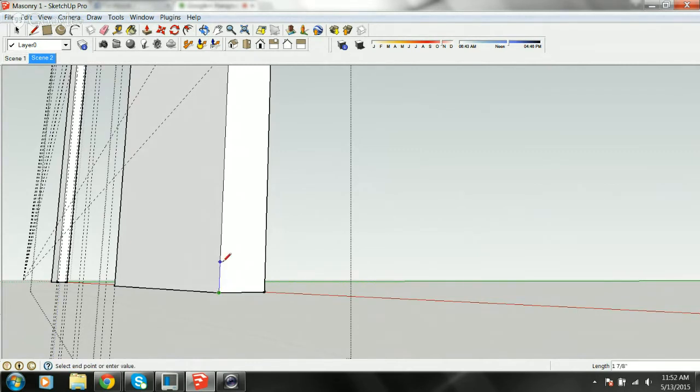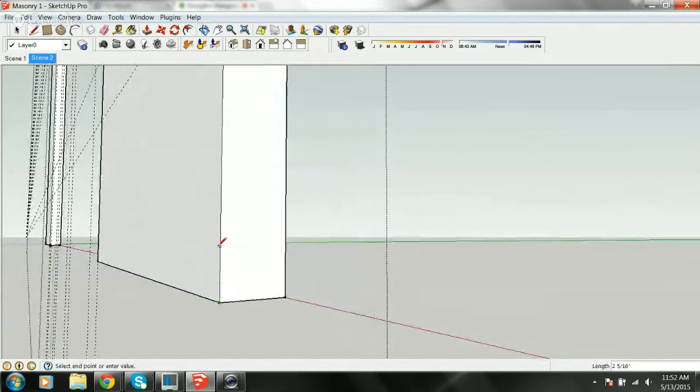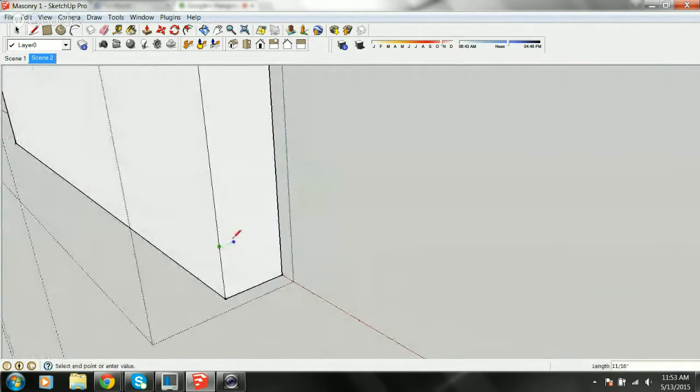We're going to start in the bottom corner. We're going to come up, and we're not going to be arbitrary. We're going to use our box in the bottom right-hand corner. We're going to come up 2.5. If Scott leaves that mark, we're going to grab it. I want red. I want green. The red axis pulls towards me. So I'm going to go 0.5, 0.5, back out to the front, 2.5. See, it grabbed it automatically. If it grabs it automatically, work with it. Yeah, 2.5. Don't fight it. Exactly.